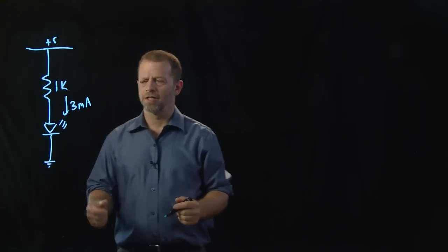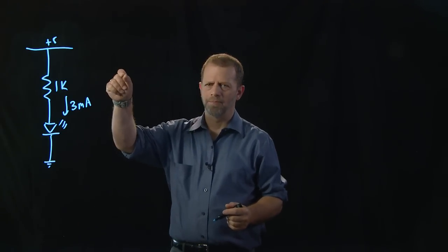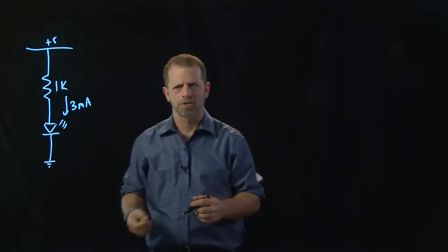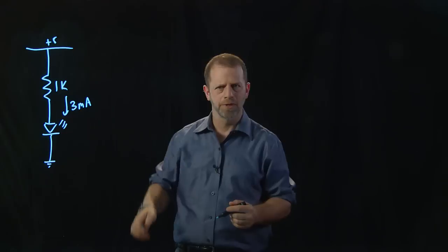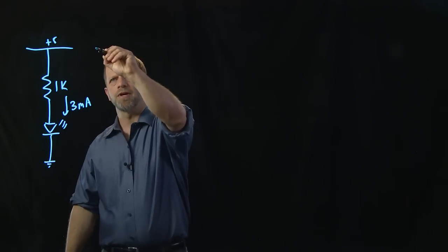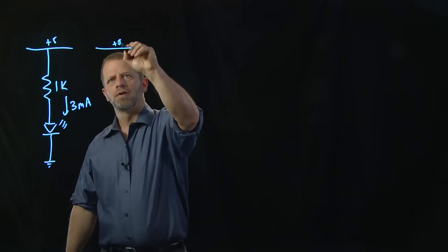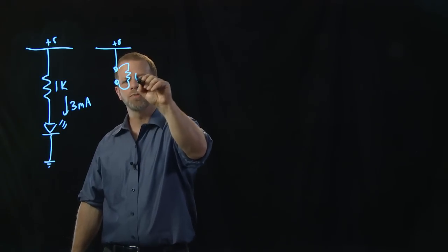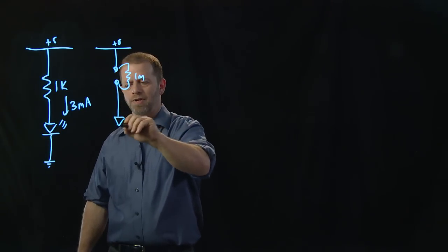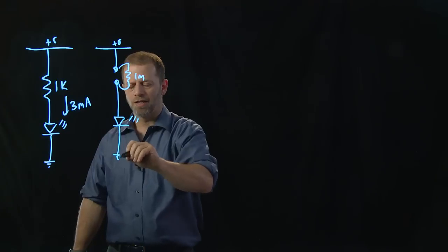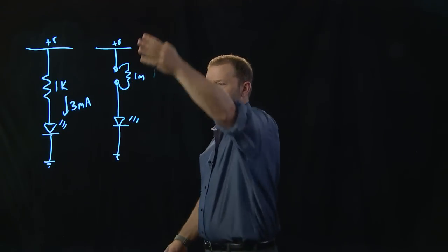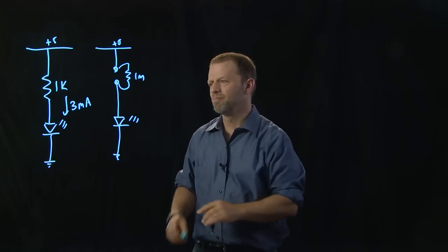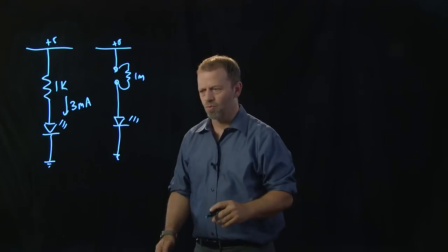Suppose you wanted to turn on an LED by pinching something with your fingers, because your fingers will conduct electricity a little bit, but not very much. The resistance of your fingers may be about 1,000,000 ohms. Well, you could say, I'll set something up like this. Here are some places I can pinch with my fingers, which are equivalent to maybe 1,000,000 ohms. And I'd like that current, if it happens, to go through an LED and light it up. That won't work very well because the current going through here is only on the order of a few microamps, unless you get your fingers wet and squeeze real hard. Maybe that would help. But anyway, it's hard to get this to work well.